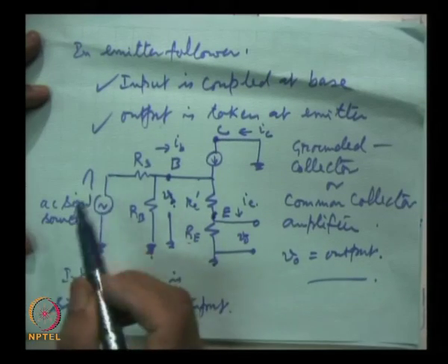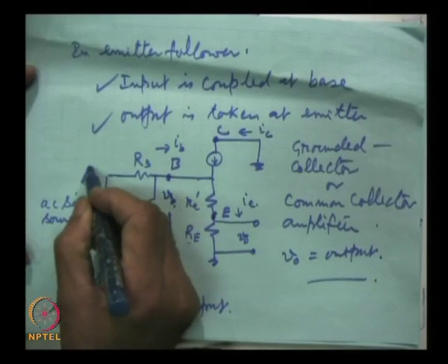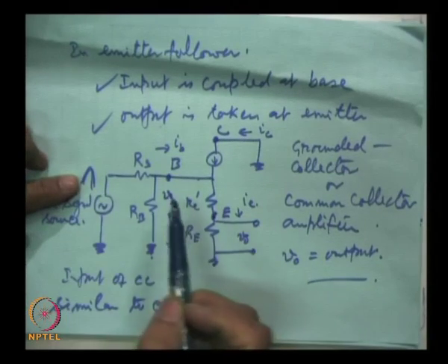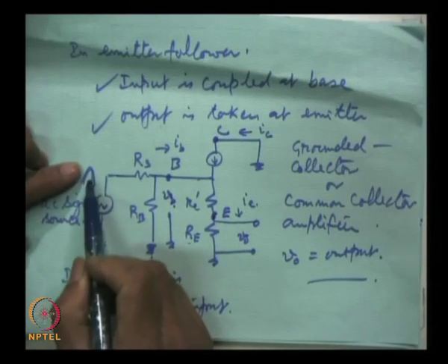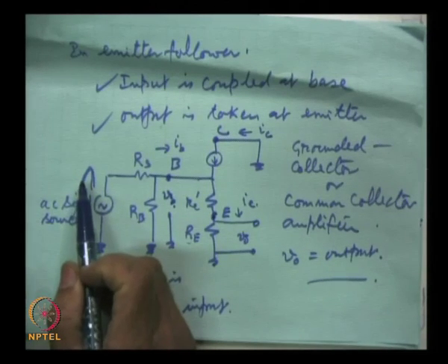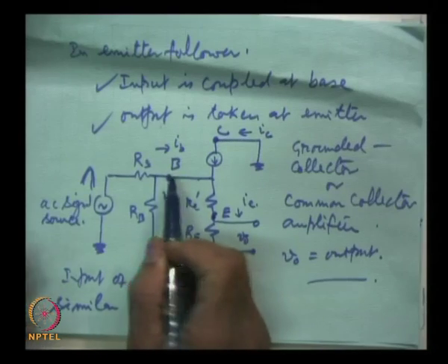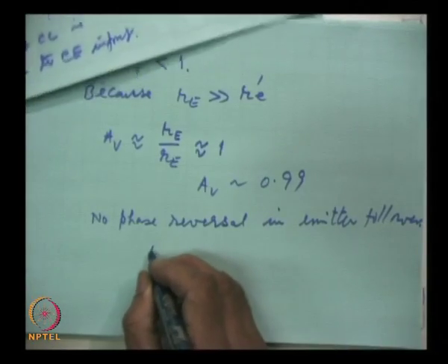Now, this is the AC signal, and when this signal is positive, it goes up, because there is AC and DC simultaneously. So, this will add up with the DC signal, and hence when the input signal is at peak positive, then the base current I_B, which is varying, will be maximum at this time.